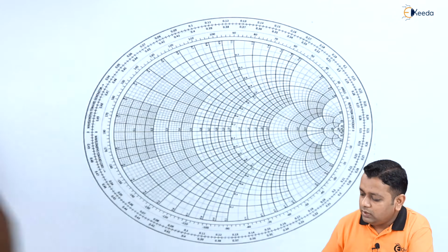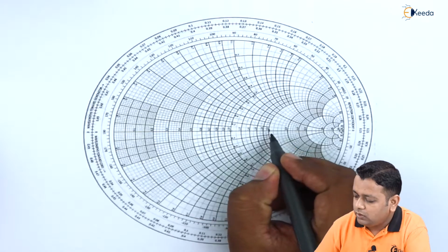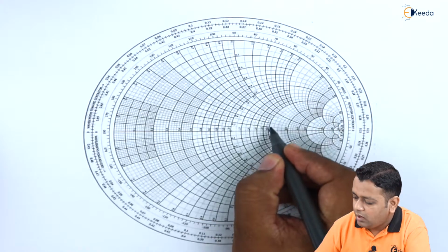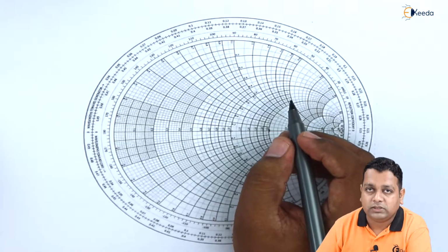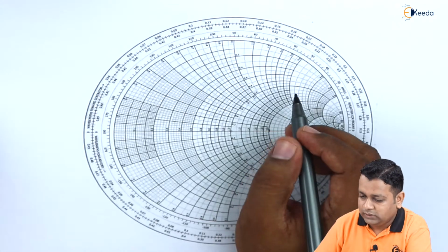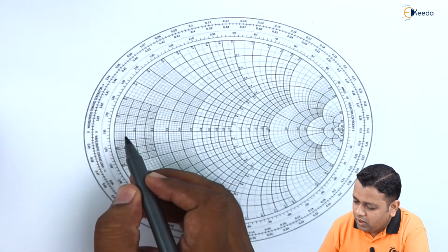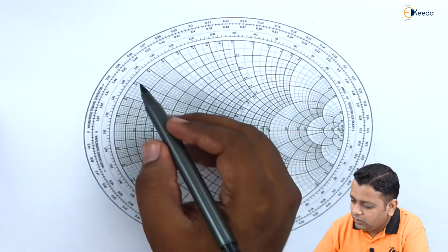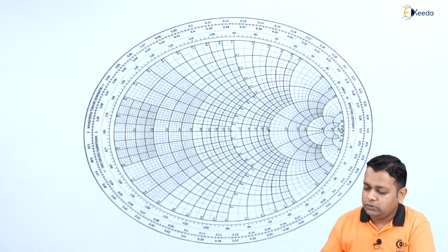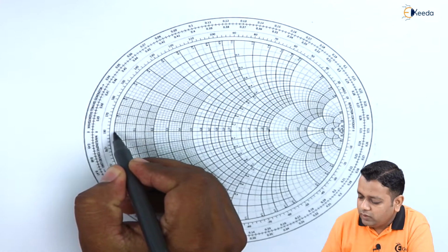So now in this Smith chart, this will be the circle with the constant resistance R equal to 2. Now we need to find X equal to 3.732. If you start here, we have the 0 values. The X equal to 0 value starts here.